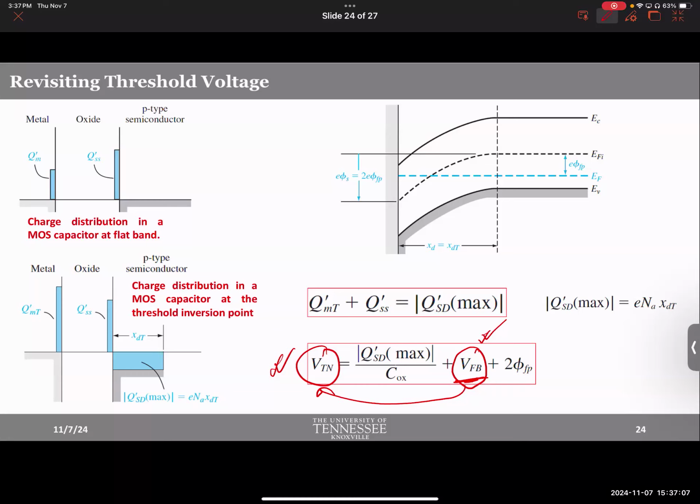Apparently, I haven't shown you that yet. This is coming up. You see, everything is linked together. I have that end product in mind. I cannot show you right away because it's going to be too misleading otherwise. Threshold voltage is linked with how much current a transistor will draw. It is not just linked with when it will turn on. It is also linked with how much voltage. If your threshold voltage is 1 volt, you need at least 1 volt to turn on the transistor. If it is 0.5 volt, you could easily turn it on, right? So if you want to deal with low voltage applications, you reduce your threshold voltage.